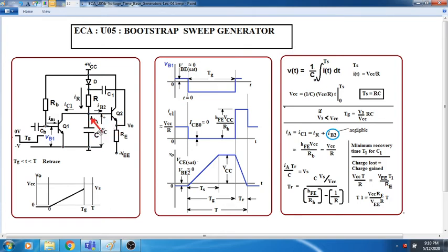So at the end point at Tg, the capacitor is having a voltage Vcc across it and it is having some charge. Okay, and this capacitor is holding a voltage Vcc here. Emitter has become Vcc. No longer is it going to increase. So we are at that position. So what is the voltage across R? It is Vcc. What is the voltage here? This is also Vcc. And what is the condition of Q1?